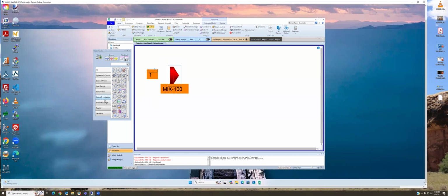Okay, then let's add a reactor. Now, what kind of a reactor should this be? Now, we've got acetone going to ketene, and then ketene further reacts to undesired byproducts. And from our study of reaction engineering, you know that's a series byproduct reaction, and we know that we want to do that in a plug flow reactor to optimize its performance in producing the desired product. So let's put our reactor there.